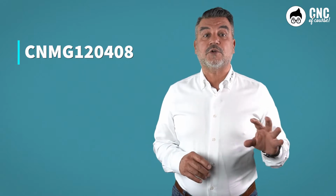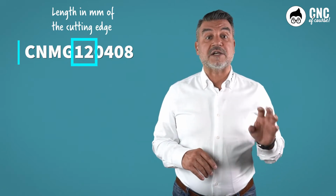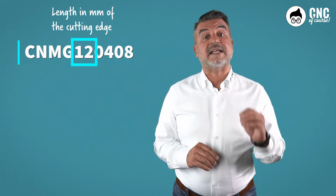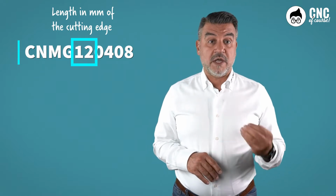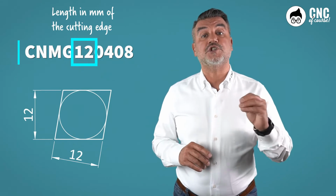Let's take our sample insert CNMG 120408. We have already seen the first 4 letters. Now let's move on to the first of the 3 numbers, parameter 5. In our case, it is 12 and determines the length of the cutting edge in millimeters. So our insert, which has the shape C, has the side of the rhombus equal to 12 millimeters.